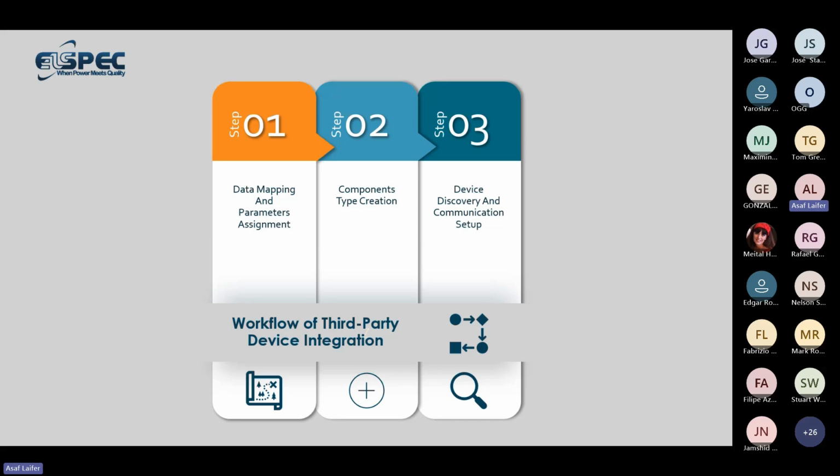And each register has a specific number or specific ID. Now, different vendors have different registers or different mapping to their parameters. So in one equipment, register number 200 can be the voltage of phase 1, and in another equipment, register number 200 can be the current I1 or frequency or any other parameter.